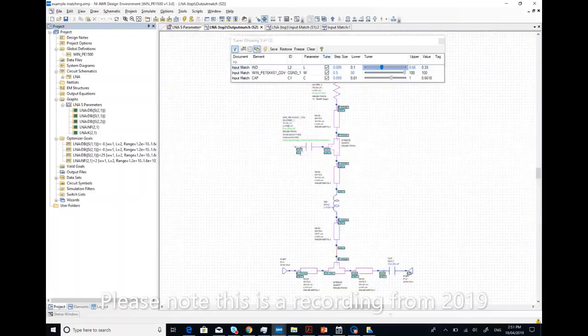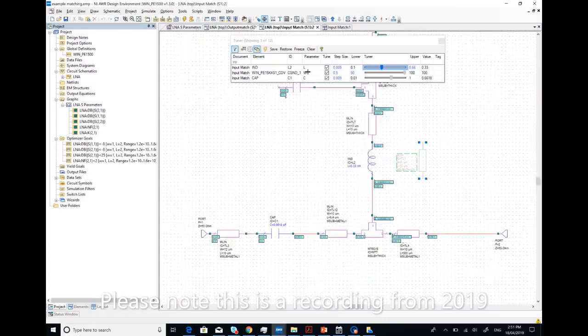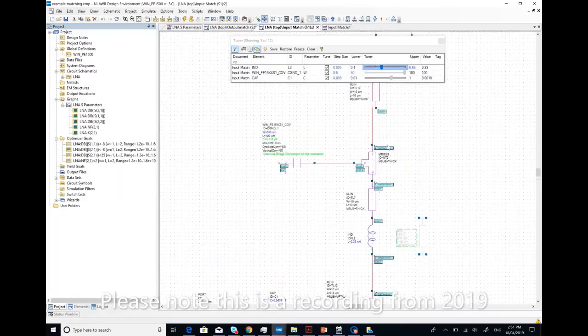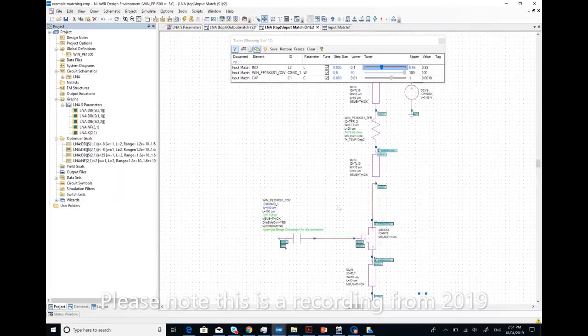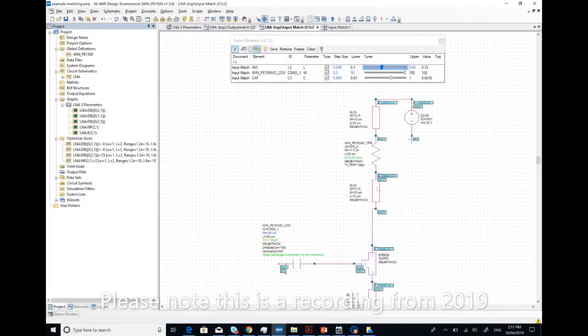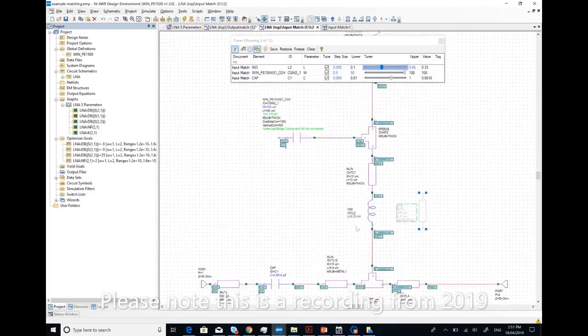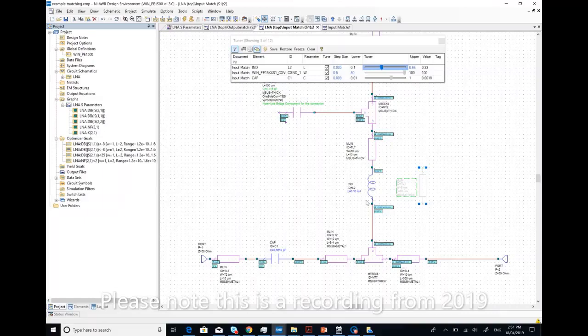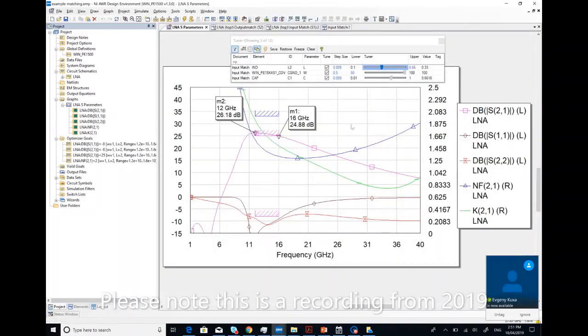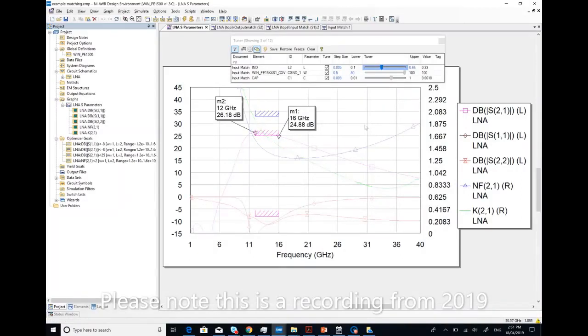So it will take you a long time because you will only have the L and C values. When you add the other stuff, you have inductors, capacitors, resistors, all of these will change your value. So it's best to tune and get a feeling for it, and this is what's followed practically when you do tuning. I come back here, say I'm satisfied with this, and press Control F to freeze the trace, because I'm going to change the components now.